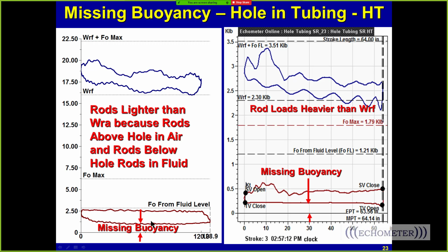And so when you get down to the bottom, the pump card's not on zero because you have extra buoyancy that's not being applied to the rods, that's missing. So the rod string actually weighs more than what it would weigh, the weight of rods and fluid. And that's this distance from here, weight of rods actual measured, compared to the weight of rods and fluid, a shift in the pump card above the zero load line. So that's another indication, if you use a horseshoe load cell, that the rods are not in fluid. The rods in the tubing are partially in air or gas, hydrocarbon gas.